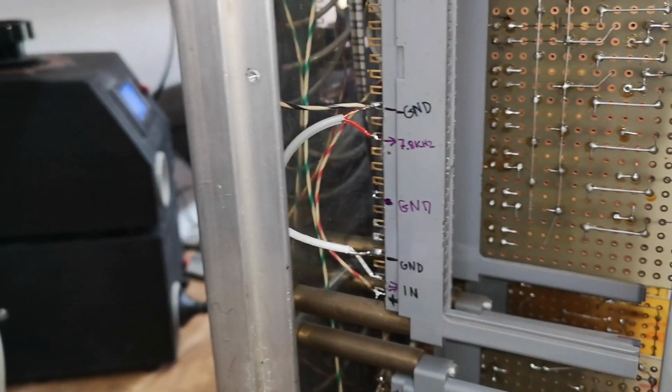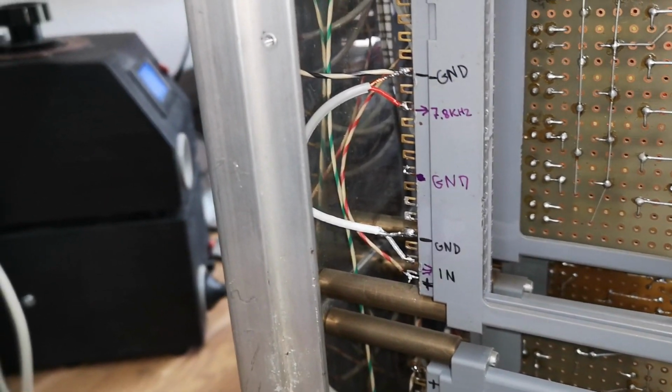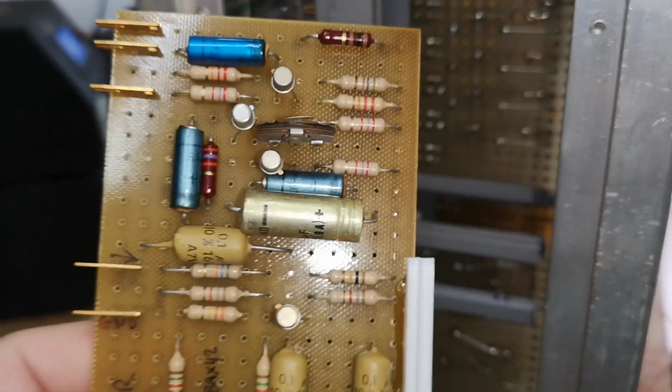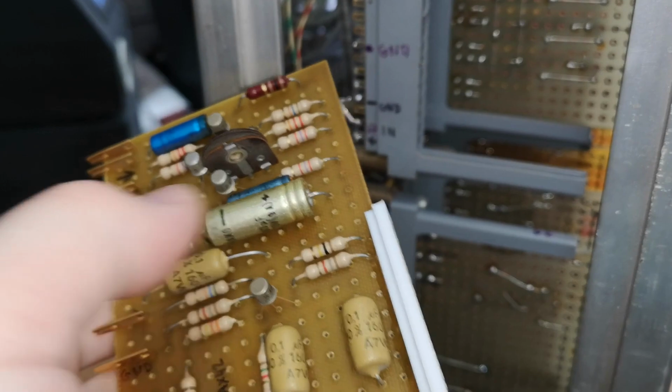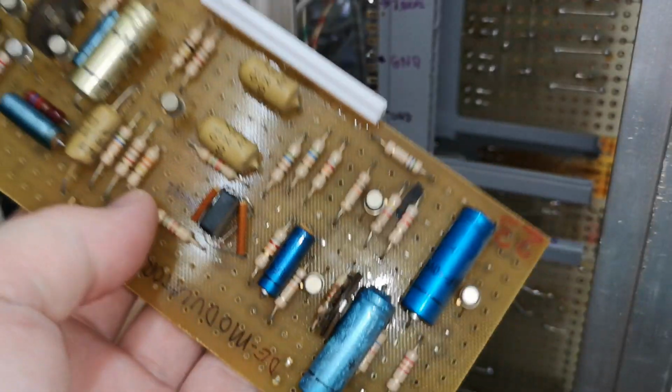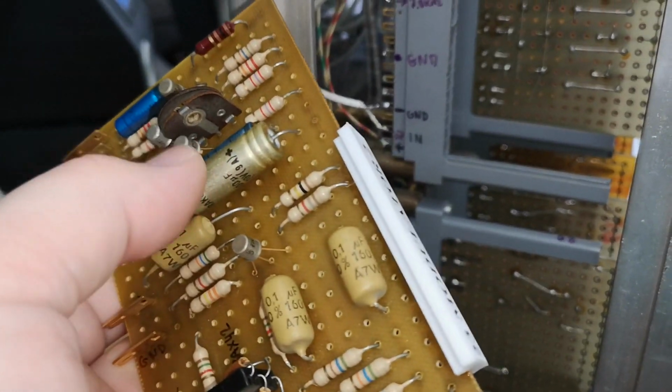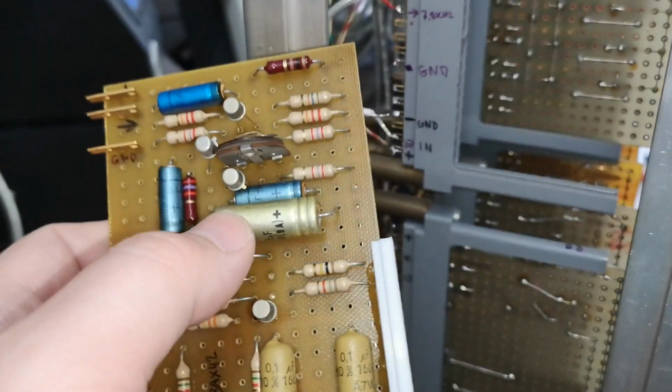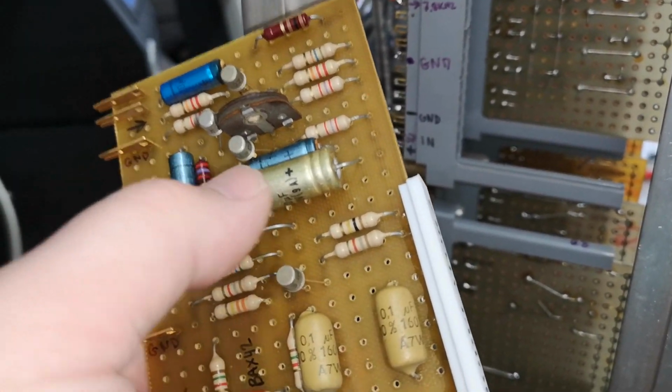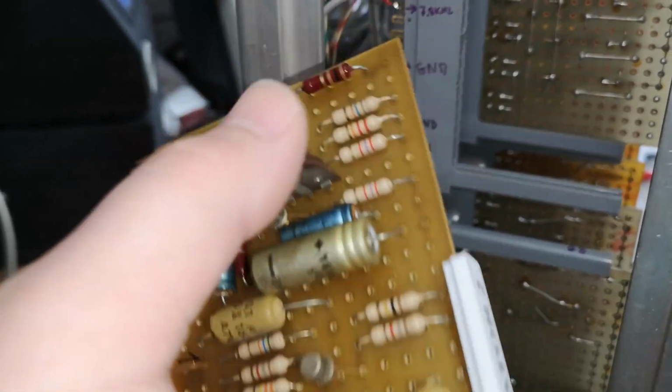Of course, this is never going to work, and it's only going to make stuff much worse. So what I did is I put the capacitor and the resistor on the board, so the decoupling capacitor is local to the board you want to decouple. This is absolutely fundamental and very, very important to do.